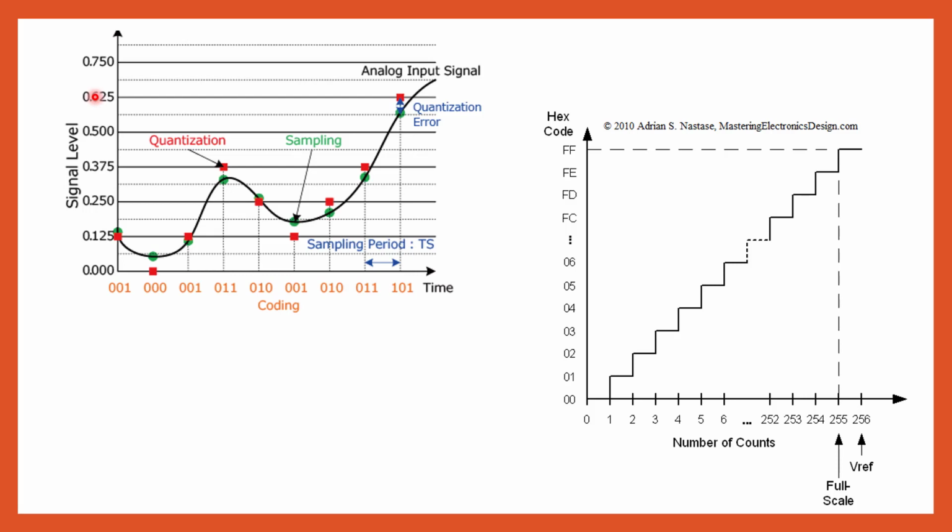But how frequently do I have to do that? And how precise do I need that to be? Do I need to measure every second to see if there's been a change in temperature? About every minute? No, I could probably wait and measure every 5 minutes, 10 minutes, 15 minutes. I don't have to have that level of precision that comes with very fast sampling because the changes that are occurring in this room or this process aren't changing rapidly enough where I'm going to miss something. That's not the case with every process.